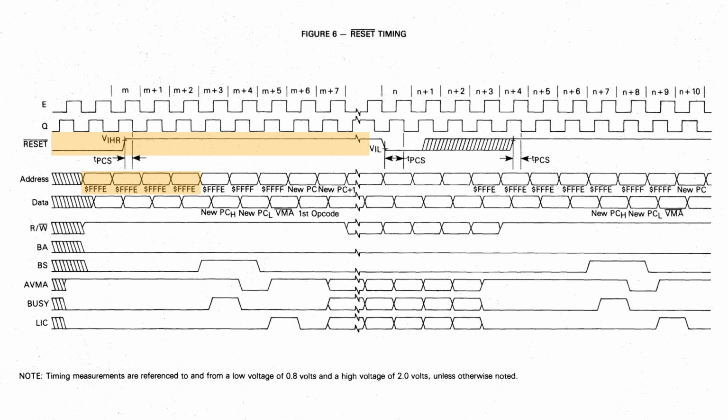As you can see from the timing diagram, the reset signal only needs to be held low for a single cycle in order for the reset to take effect. Once it does, the CPU keeps repeating the address of the reset vector until the reset line goes high, and then again for the next 3 cycles, after which the bus status signal goes high, indicating a vector fetch, which then takes the next 2 cycles, followed by a dead cycle, followed by the fetch of the first instruction pointed to by the reset vector, which actually takes 2 cycles because the 6809 instruction fetch always fetches at least 2 bytes. So our job today is to do this right here.